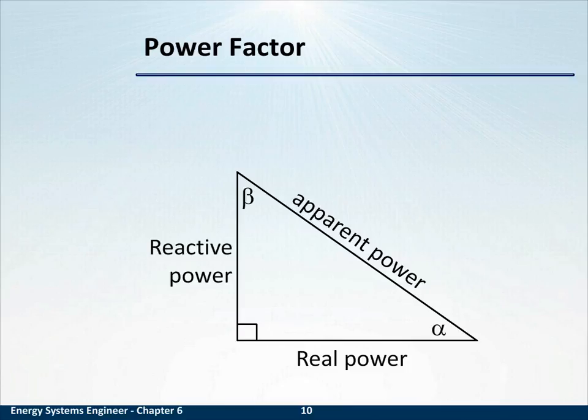So what does it mean to have a desire that the power factor equals 1? Let's consider power factor along with efficiency as it pertains to load. Let's look first at efficiency. 1 horsepower, 10 horsepower motors. Both of them, you see that if they're underloaded, the efficiency goes down.